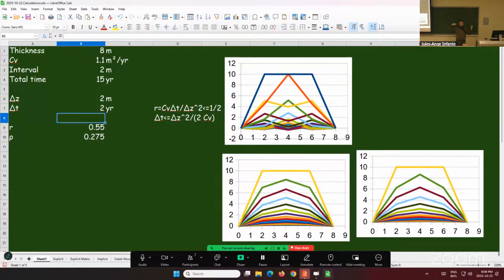But keep in mind that it has the same basic limitations, right? Because information needs to propagate through your elements, through your mesh. So depending on how small your elements are, you can compare the smallest elements to that mesh size here and see how stable to expect.